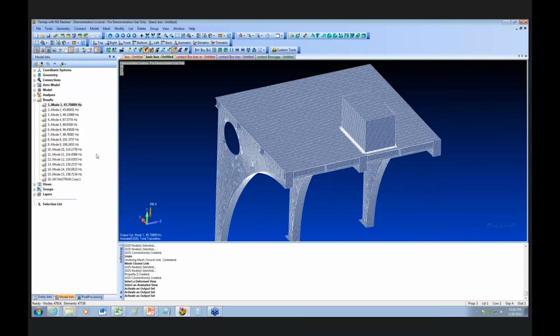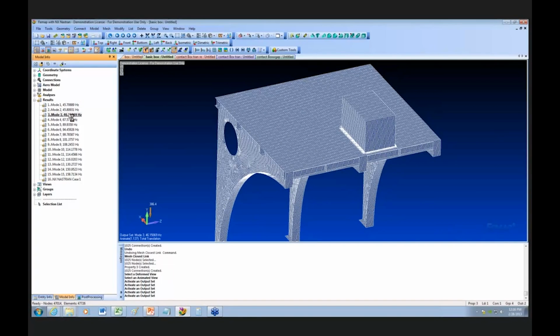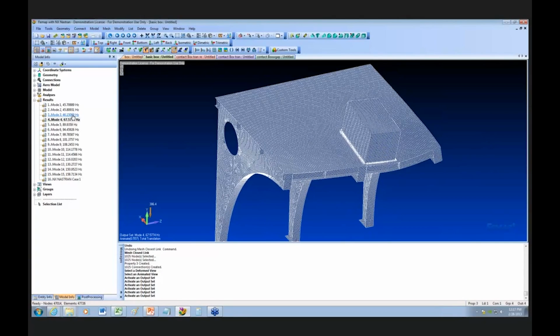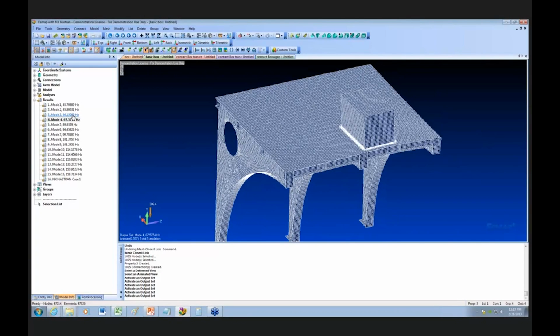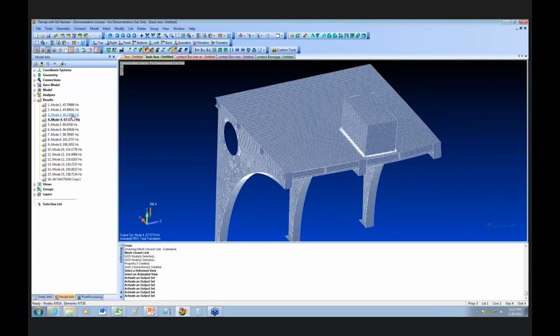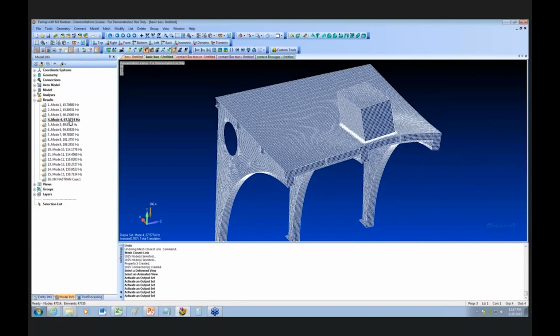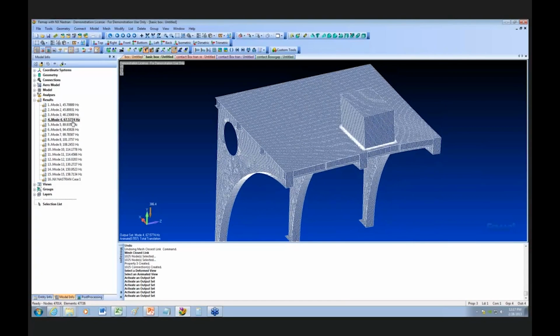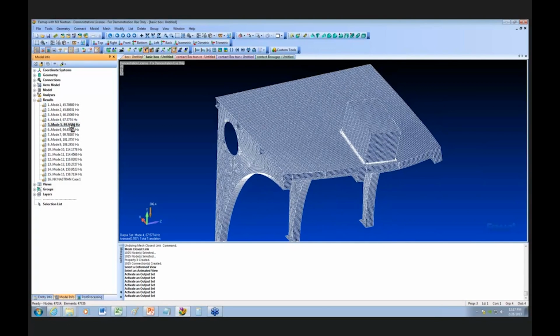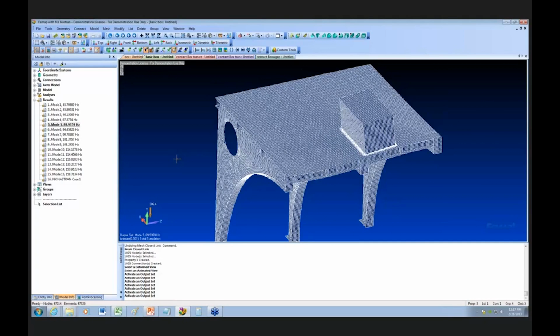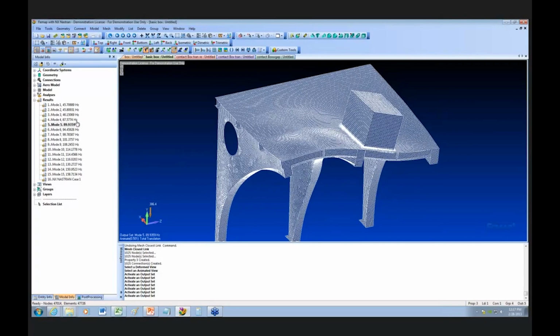It's not going into that mode shape. So you go down here and look at how this box would respond with the frame when it makes contact. I believe energy would go into this mode right here, and we need to note that 67.6 hertz, okay? We keep going down through here. I'd say that energy would probably go into this mode as well.